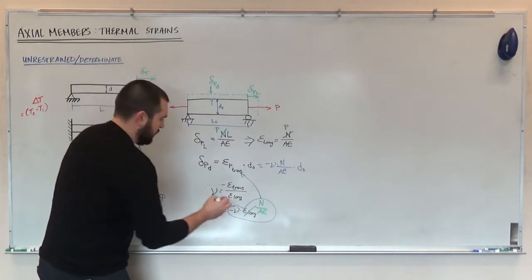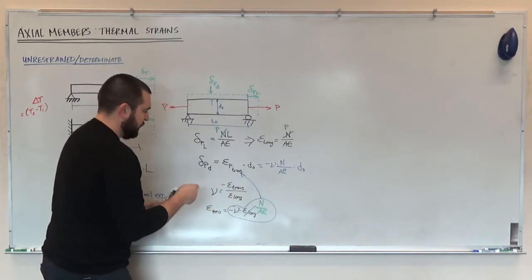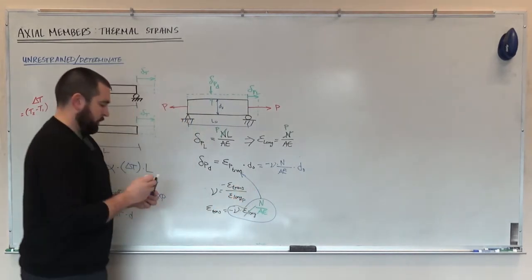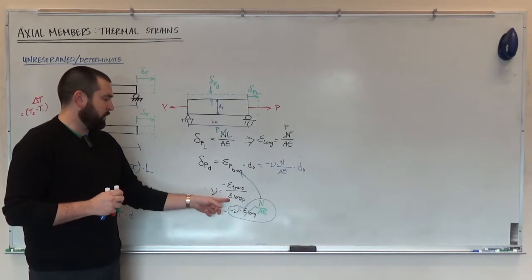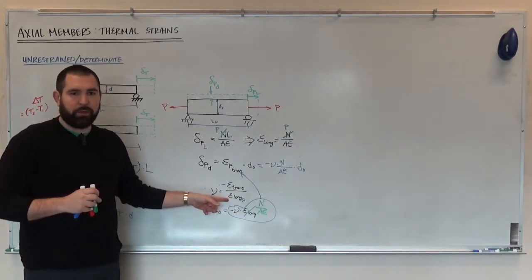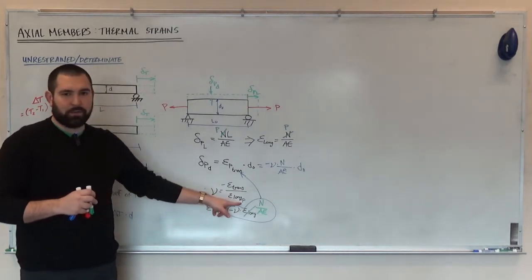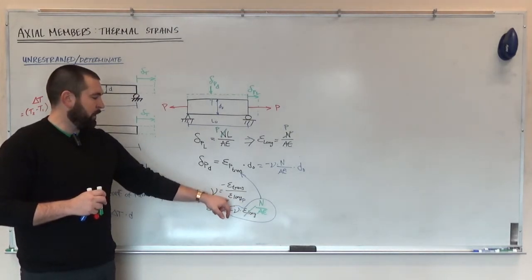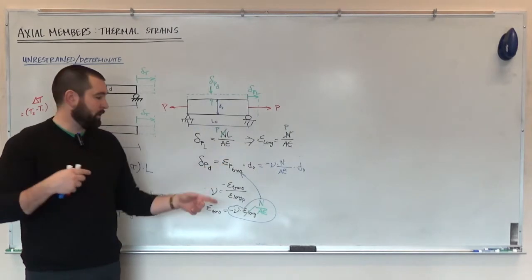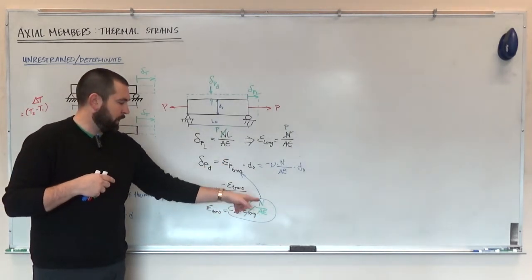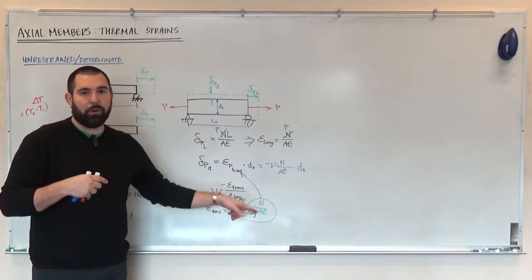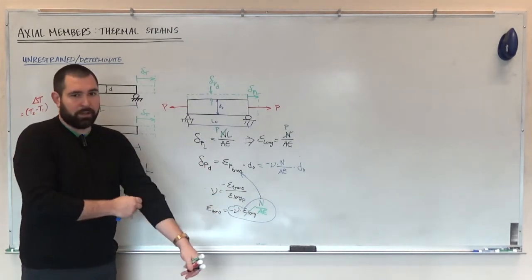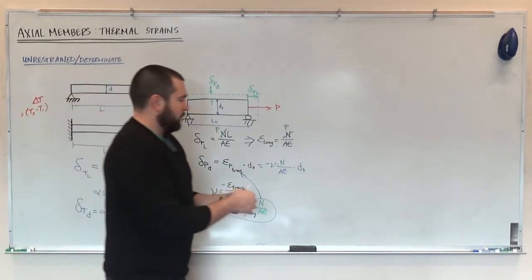So I'm going to put a subscript P on each of these, or on the longitudinal, it only cares about how much longitudinal strain is caused by the external load. You wouldn't calculate the longitudinal strain here, including any thermal effects. This is only going to be the N over AE type component, only the longitudinal strain due to the externally applied loads.